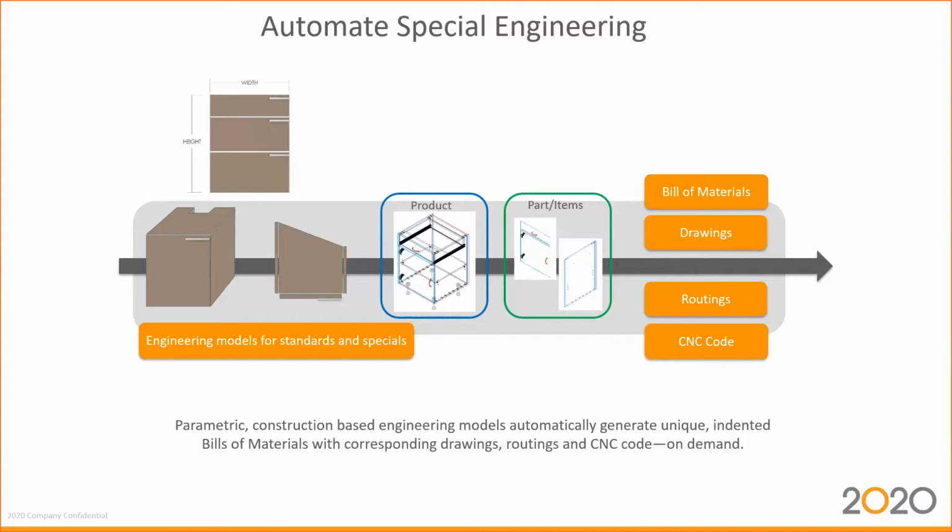And finally, we're generating the final CNC code here based on the geometry data of the parts and how these parts are touching each other. We know exactly what's the connector, if it's the dowel, if it's a hinge. We know exactly how the drilling pattern looks like.